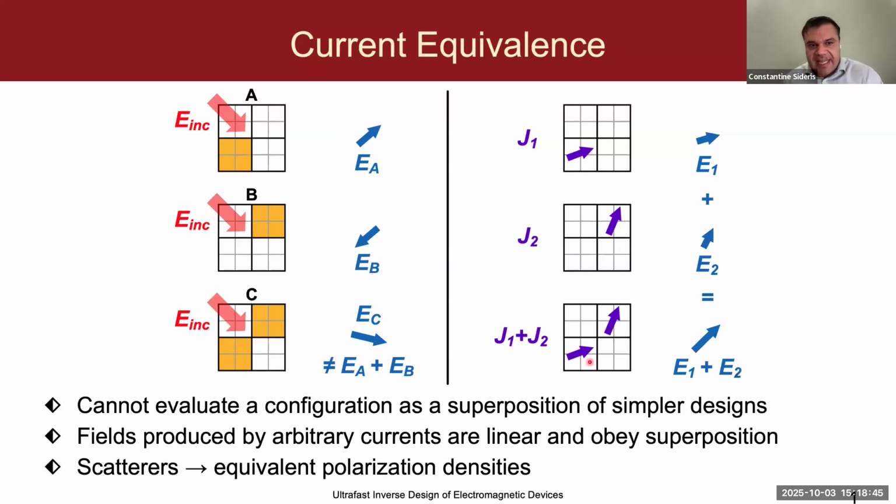So this sort of presents a sketch of an idea, which is that instead of pre-simulating metal tiles, we can actually pre-simulate current densities. And then based on the current equivalence theorem, there's a surface current equivalence theorem of Maxwell's equations, which is the foundational basis of integral equation methods. But based on current equivalence, we can actually find the amplitudes for the currents that are needed to satisfy the boundary conditions for Maxwell's equations and result in exactly the same fields as if we had simulated the metallic problem wherever we had these current densities.